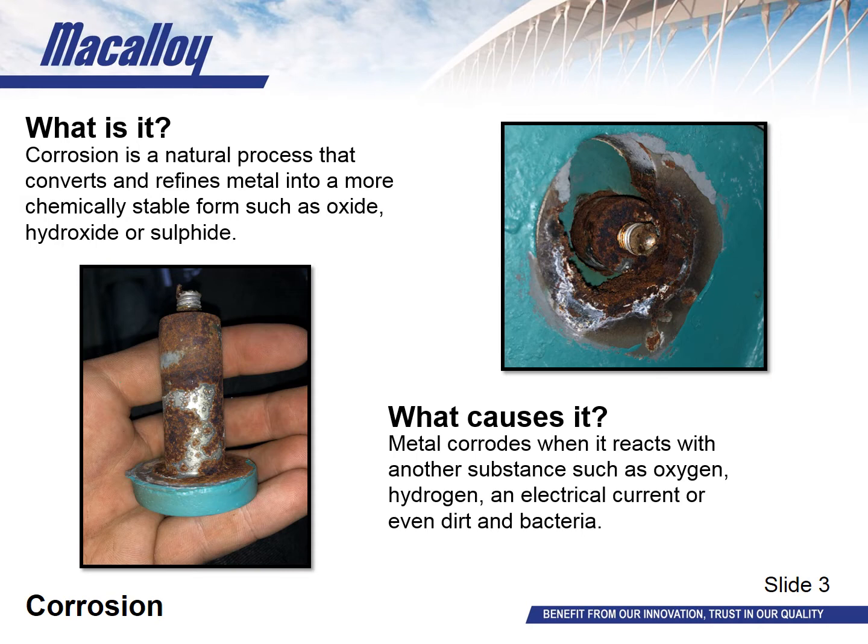A 316 stainless steel pin was used, however, as you can see, severe corrosion occurred. The paint was not applied correctly to the carbon truss, and as a result, bimetallic corrosion transpired. As a result of poor maintenance, moisture was able to pool within the slot of the truss, thus leading to crevice corrosion. Macalloy were asked to survey the structure and assist in supplying replacements in duplex.